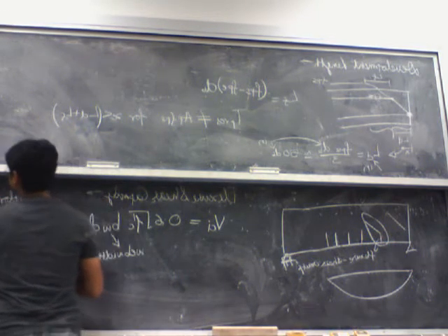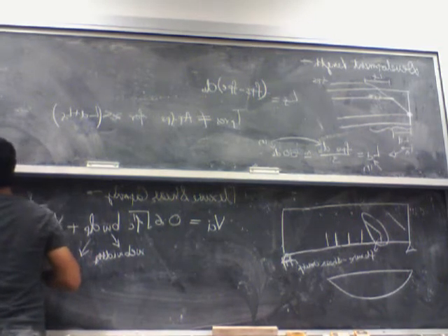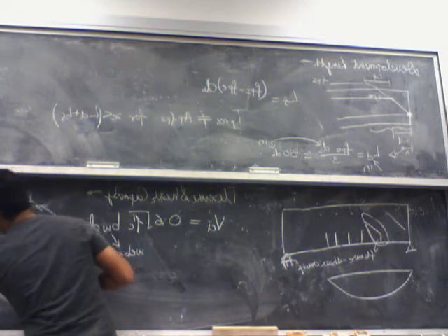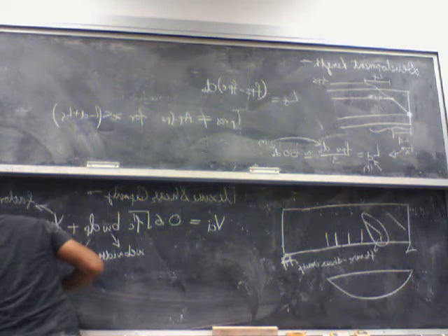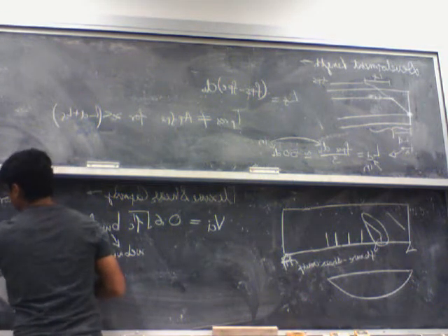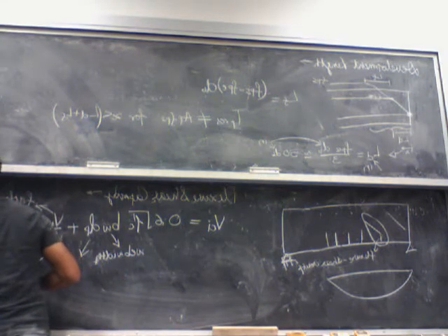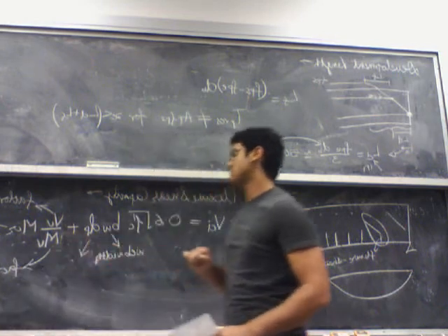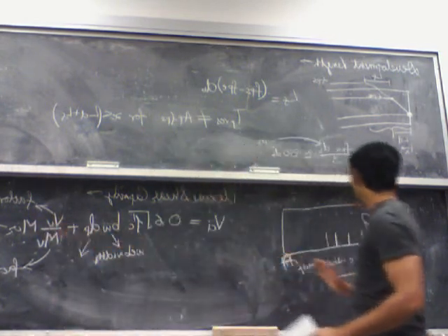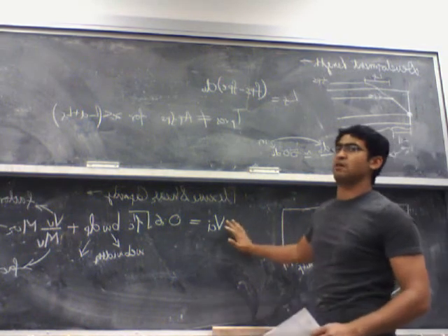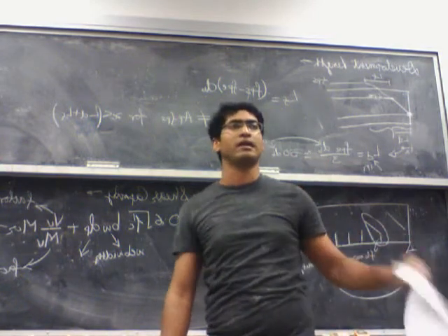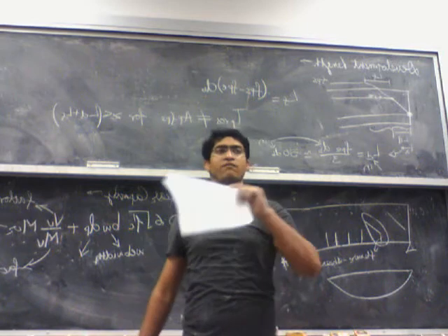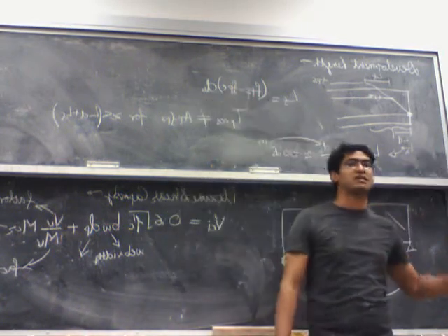This is the factored shear demand. This is the factored moment demand. And this is your cracking moment. So when I say the factored shear demand and the factored moment demand, what you are supposed to find out is V_u, the shear at any given cross section due to the factored loads. By factored loads, it's 1.2 times the self weight plus 1.2 times the dead load plus 1.6 times the live load. Similarly, this M_u is the moment caused by the factored loads. Again, the factored loads are 1.2 times self weight plus 1.2 times dead load plus 1.6 times live load.